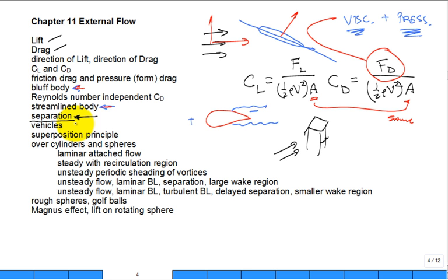Yeah, it's really good to understand the flow that goes around the cylinder. That's the easy one. So as we're going around the cylinder, if you think of this section of the flow, that quadrant of the flow, what's happening to the velocity as you're going from point, let's say, A to point B? What's happening to the speed of the flow? It's going faster and faster, isn't it? So it's accelerating.